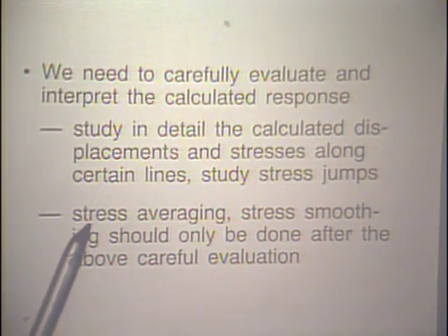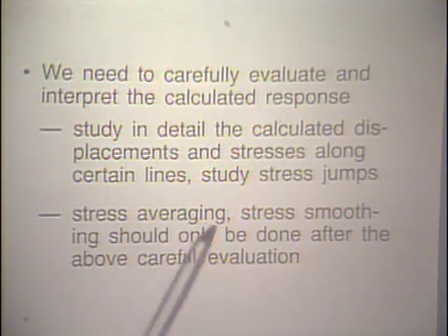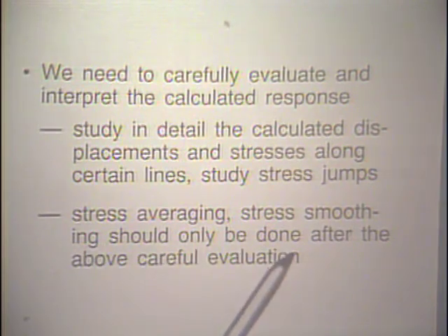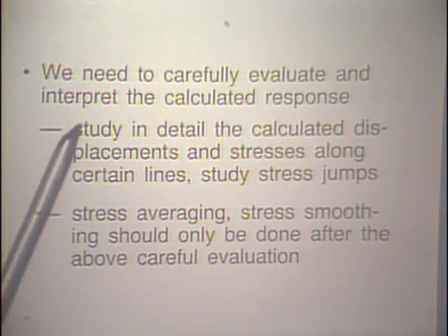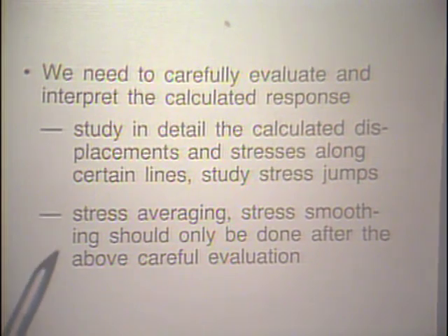And here I'd like to add that stress averaging, stress smoothing should only be done after the above careful evaluation. That's something important to keep in mind. I believe that you should first look at the stresses the way they have been calculated by the program, and then start thinking about stress smoothing, only after you've gone through this phase.